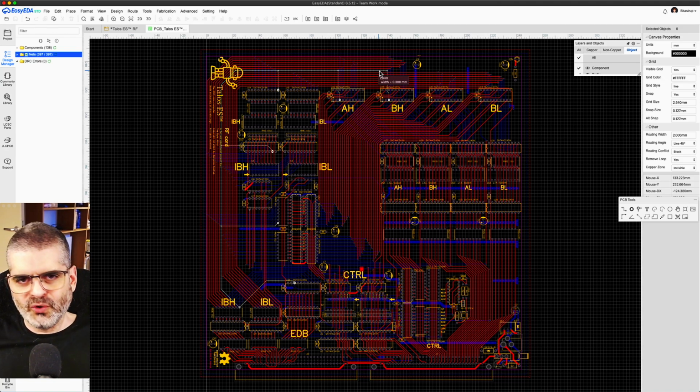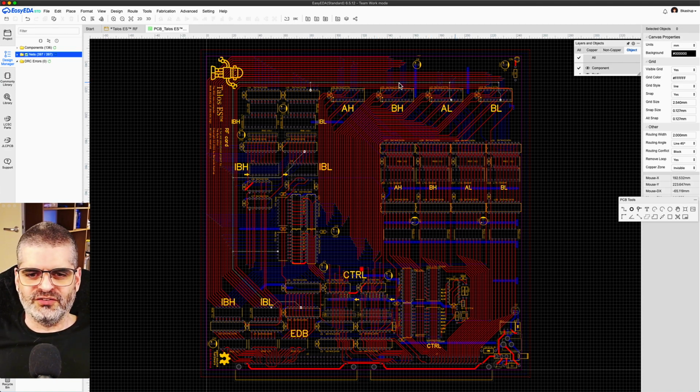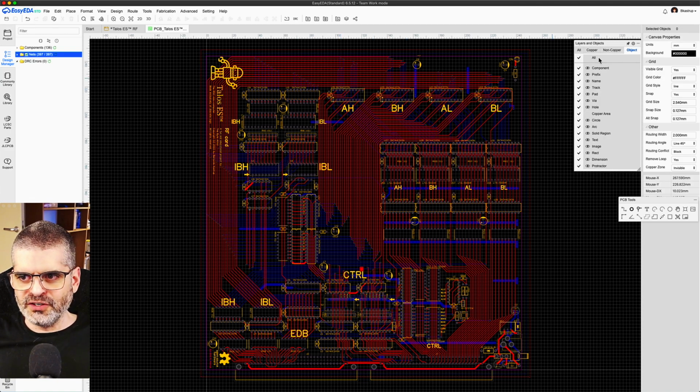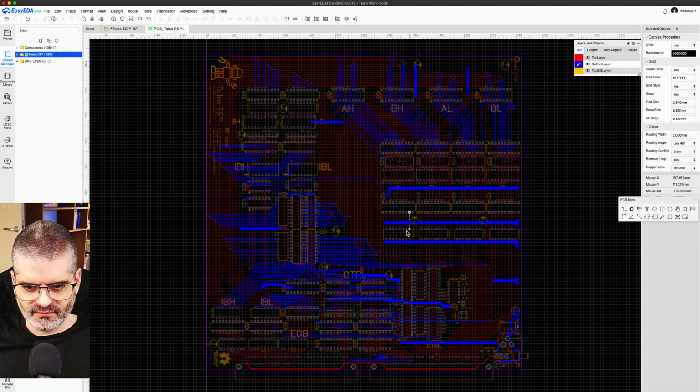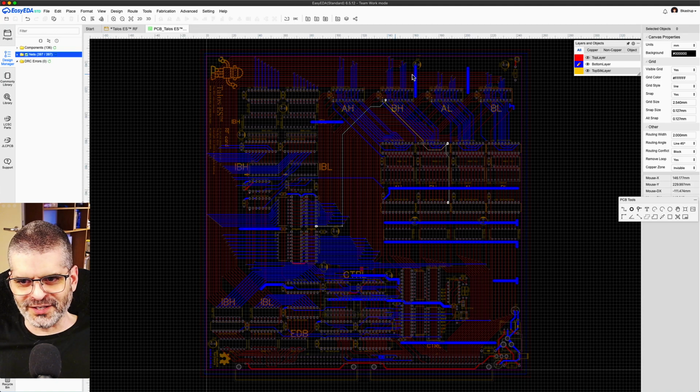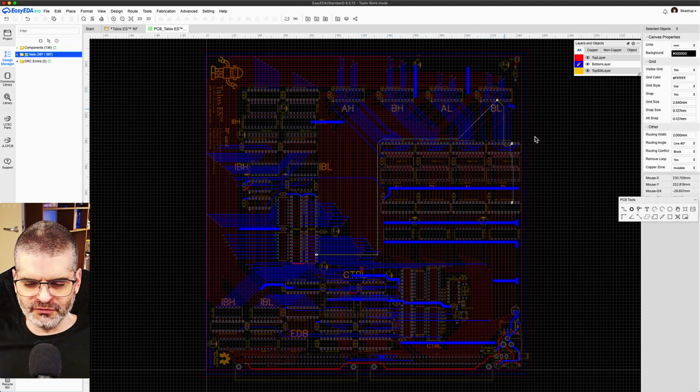In other words, one more impedance mismatch, one more chance for reflections. So I ignored the rule of thumb here, but then I inverted everything. You see, normally blue is horizontal, so that's the blue layer. Almost everything horizontal, but because I changed the convention on top, I was consistent with that. Now blue is vertical on top, you see? Close to the top, blue is sort of vertical.